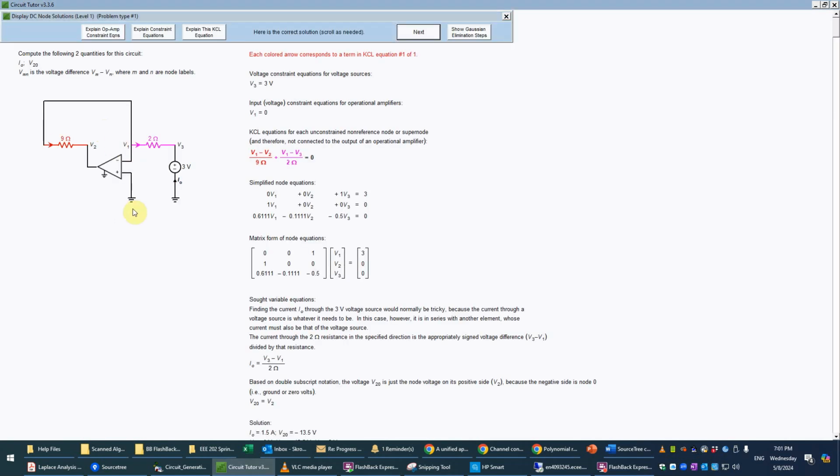And so you see here we have a problem with an op-amp, which of course is a symbol. And we notice first of all that this op-amp does have proper negative feedback going from the output of the op-amp back through the resistor towards the negative input, which is the way we need to operate it to have stable behavior.